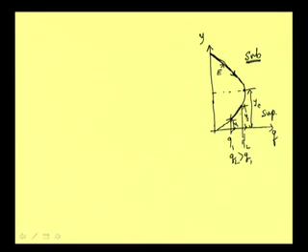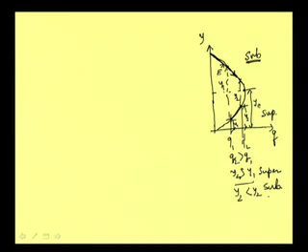So Q2 greater than Q1 means Y2 greater than Y1 in case of supercritical flow. Here Q2 is increasing, Y2 is also increasing. But if I extend this line to the subcritical zone, this is Y1 and this is Y2. So Y2 is less than Y1 for the subcritical zone.